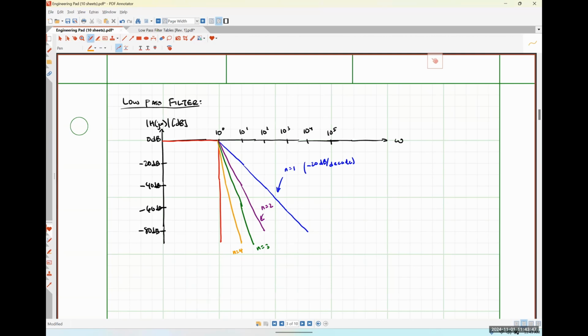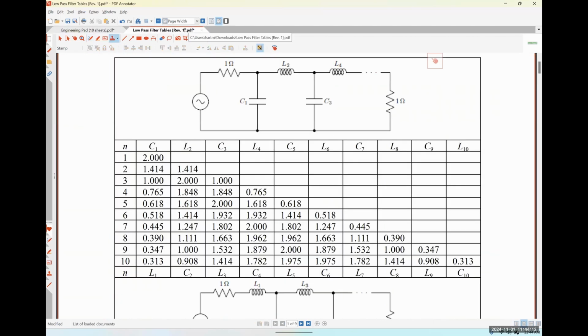So anyway, basics of ideal filter versus higher order filter and what order does. Similar for high pass and band stop, it generally behaves like this. The higher order we have, the steeper the roll off, or the steeper the transition from the pass band into the stop band. So anyway, going back to the table.